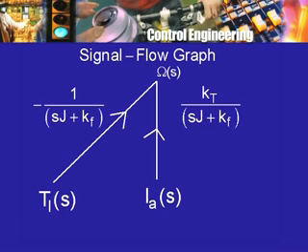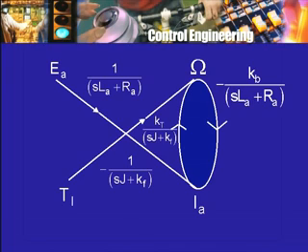So these will be the two additional lines or gain relationships, and therefore the full signal flow graph will now look like, combining the two, what will it look like? Draw it. I will now drop that S because I do not want to clutter my diagram. Here is omega, here is Ia, here is Ea, and here is the node TL.